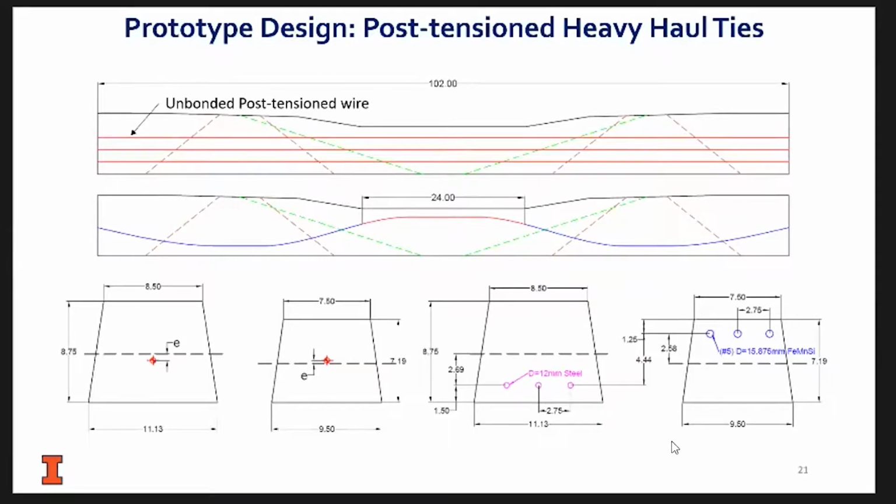Looking at post-tensioning, the same thing. I'm not going to reveal any of the details of the designs that we got from companies or who's the manufacturer is, but the bottom line is that the eccentricity there is very small with post-tensioning systems that we currently use. We can actually try to expand that. So once the E goes up, P goes down. P times E is the moment. Remember, E goes up, P goes down. P goes down means less steel. And that's the beauty of this.